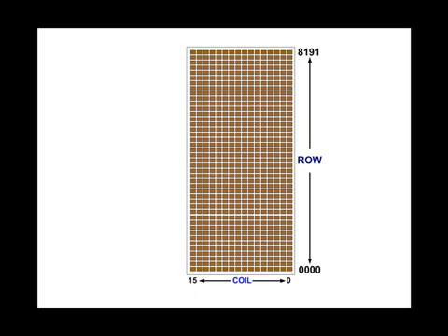Let's take a closer look at one element from this array of relays. Each element of this array has a coil that is on or off, 1 or 0. If we want to allow current to flow in another circuit if a particular relay coil is on, we use a normally open contact, and if we want to allow current to flow in another circuit if a particular relay is off, we use a normally closed contact.